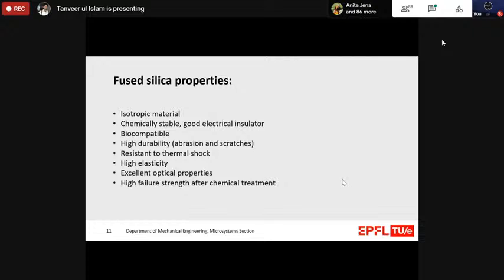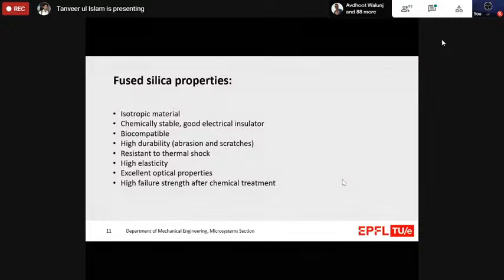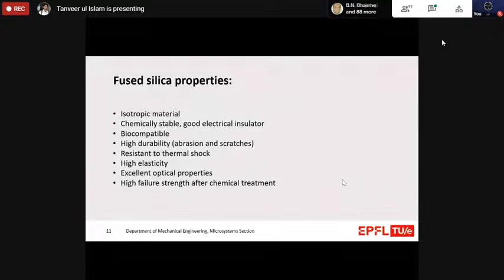So what you can do is take this laser beam and focus it somewhere in the middle of the glass substrate, or maybe on one surface, and then go down to the middle, to the center, to any other position within the glass substrate. That way we are able to modify this glass using the laser at different locations in the Z direction. So we can modify the material in 3 dimensions. Like I said in the previous slide, we take the laser beam and scan it at different points along the substrate, and wherever the focal point hits the substrate, it gets modified, and then we can dissolve that away in a chemical bath.